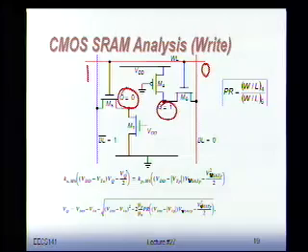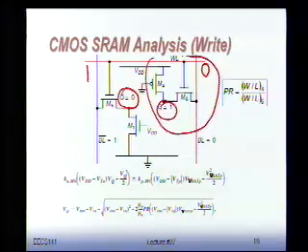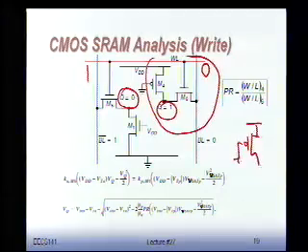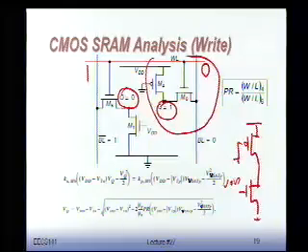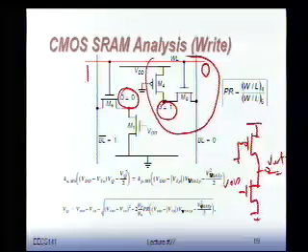So again, we have the same problem here. If you look at this structure, now we can write actually equations for both sides. You look at this structure here. Again, I have now a gate, which is a PMOS, which is grounded, and I have an NMOS connected to ground as well, and this is VDD, and this is V out. Okay, so we can recognize this structure. It's a pseudo NMOS inverter. You have a PMOS load, which is grounded, and you have an NMOS pull-down device. Okay, so again, a known thing we can solve.